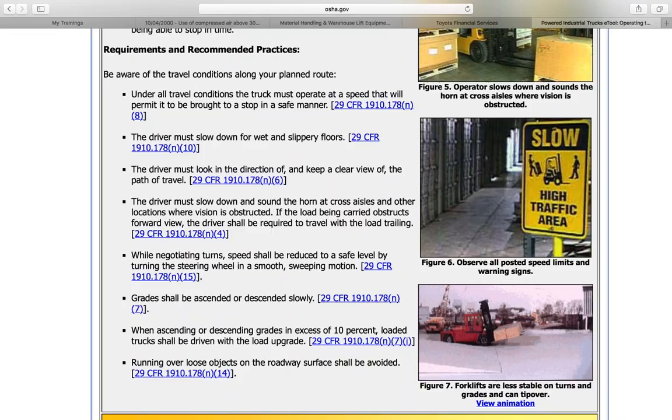All right, so let's go ahead and move on, and we're going to talk a little bit about safe operation. So let's talk about the safety rules when we want a safe operation of a lift truck. I'm at page 15, module 7, on the right-hand column, about midway down. Things we want to do: always check the capacity of the load chart mounted on the machine before we operate it. We want to know what it's capable of picking up, and we also want to know at what angles we can pick it up.